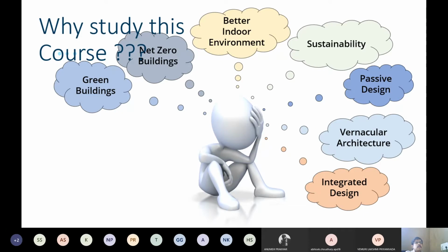We are talking about a thick wall. These stone walls in Rajasthan. I have stayed quite a bit of time in Rajasthan, so I can take some examples from there. These walls that are used in the forts in Rajasthan, those thick walls, they are a part of this passive architecture, a passive design strategy. They are a huge barrier against the heat from the outside, one of the cheapest construction materials available in those days, and it doesn't let the heat come in, thereby giving a huge level of thermal comfort indoors.